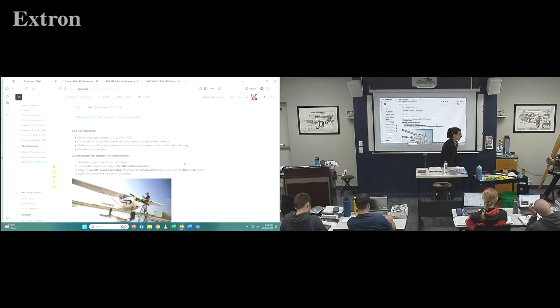And these brushes, I gave each group a cart so you could put your brush on the cart. If for some reason you have to lay it on the ground, make sure you're laying it brush side up. If you plop it on the ground like that, guess what? You're grinding dirt into your nice, clean aircraft. Do not do that. You'll get marked down. That's fair.